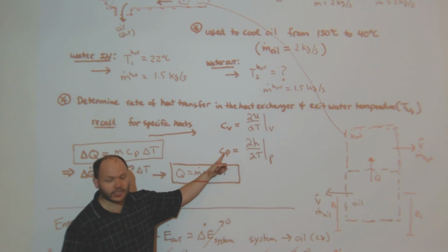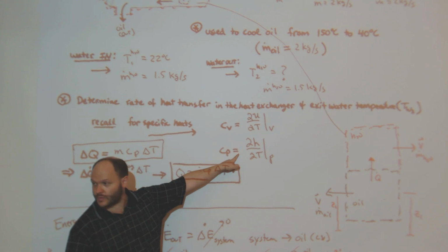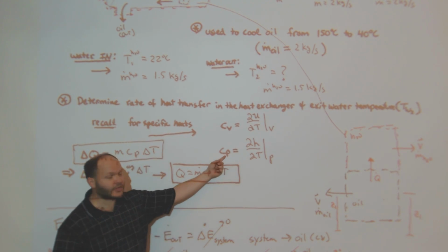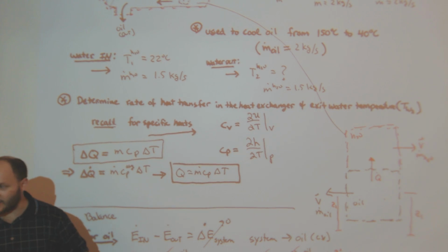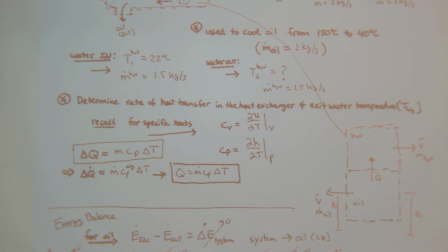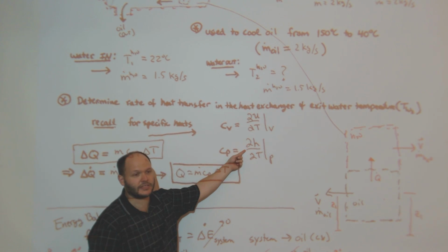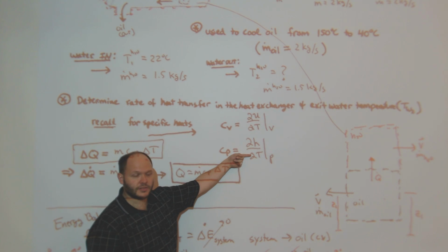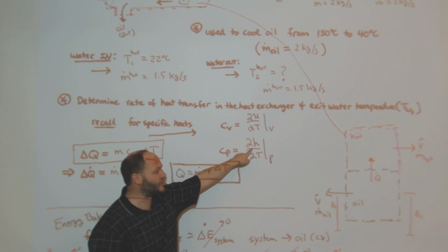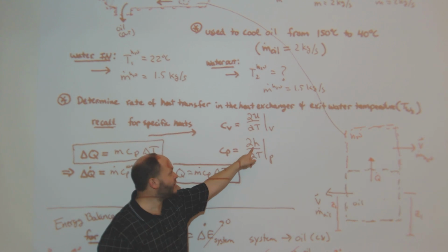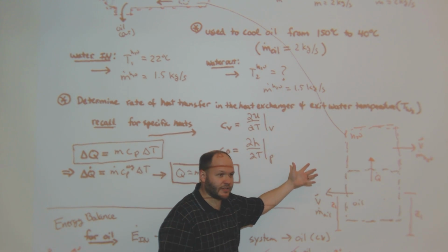And you can always rewrite this, and remember this is a derivative, so you can integrate both sides. And now you have the change in enthalpy related to the specific heat, and so if you have the specific heat at a couple of temperatures, you can calculate H. You'll probably do something similar with something you're dealing with as an engineer later on, if you deal with heat transfer type things. This won't be tabulated, so you'll just look up what somebody measured at a couple of different temperatures, and then you'll use this delta H to predict the change in entropy, which we'll get to later on.